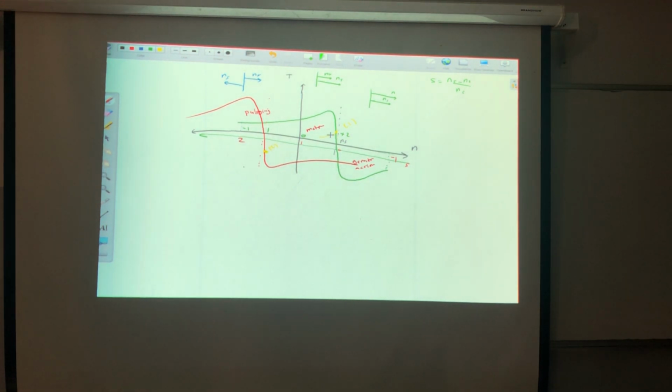So simply this means that I will go from 1 to point A. The speed is the same. The torque reverses direction. So I will do what? Deceleration. Crossing the zero. Then accelerate in the opposite direction. Correct?